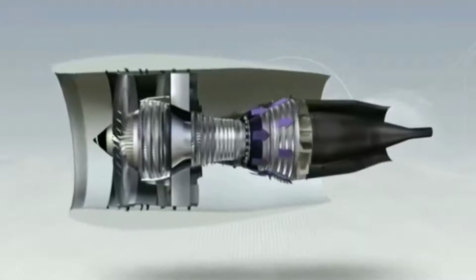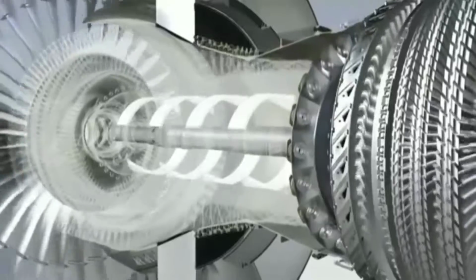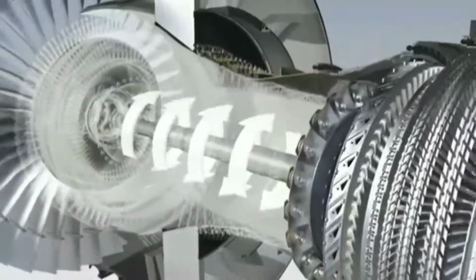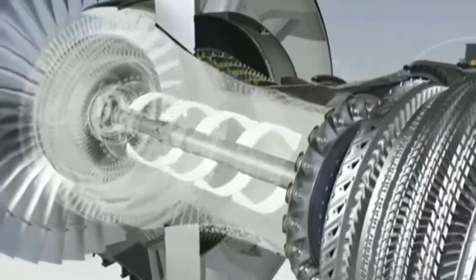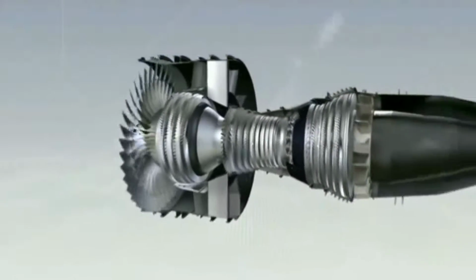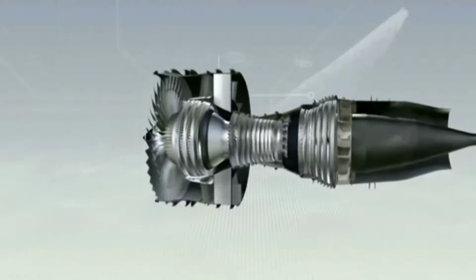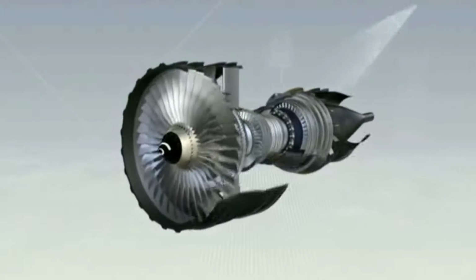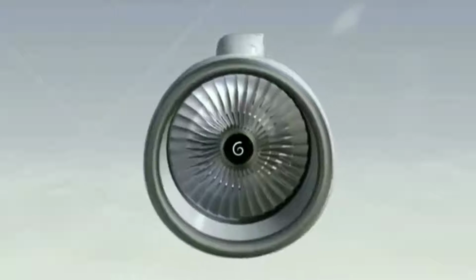The animation shown here is a turbofan engine with high bypass ratio. Bypass ratio is the ratio of the mass flow of air bypassing the engine core divided by the mass flow of air passing through the core. 10:1 means 10 kg of air bypasses through a duct for every 1 kg of air passing through the core.